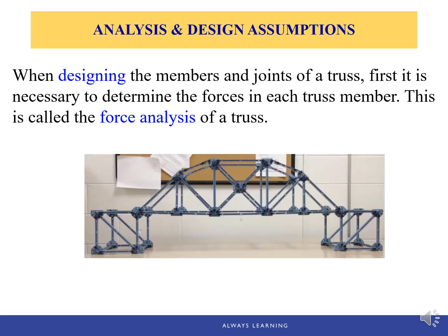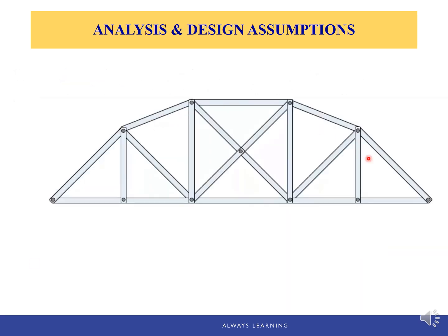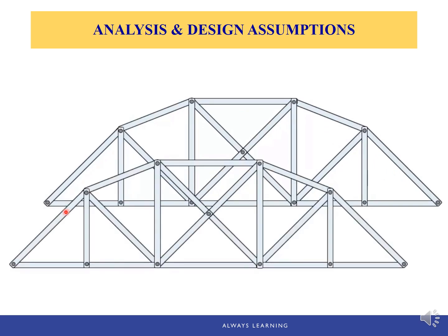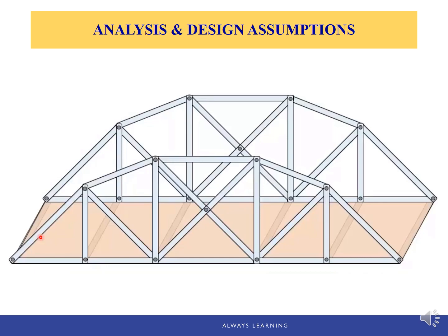And here is a picture of a model truss bridge, which is built with only slender beams. Let's analyze this bridge span. It consists of a back panel and a front panel. The back and front panels are connected with floor beams. And on this floor beam, we can add a deck. And this is the surface to provide support to the cars or train that cross the bridge.